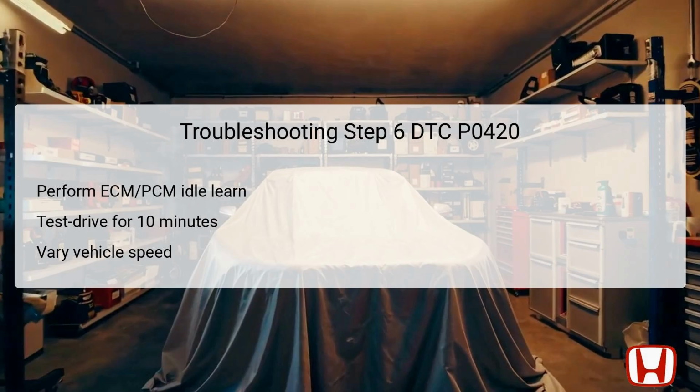Following the idle learn, a test drive should span approximately 10 minutes, where the driver must consistently vary the vehicle speed to mimic real-world driving conditions. This variability assists in adequately calibrating the newly installed catalytic converter, ensuring that the ECM can effectively monitor its performance.